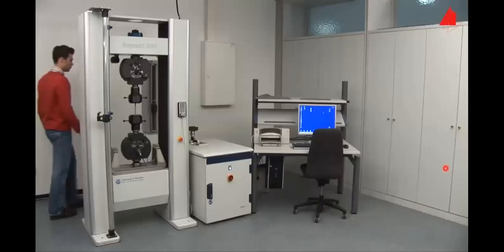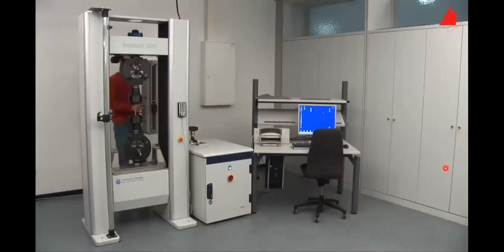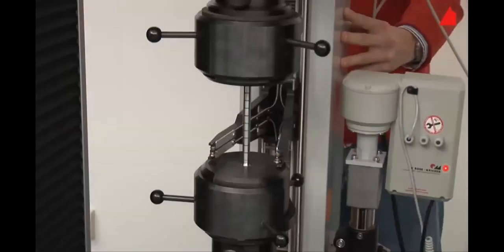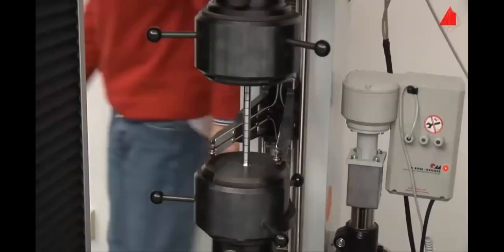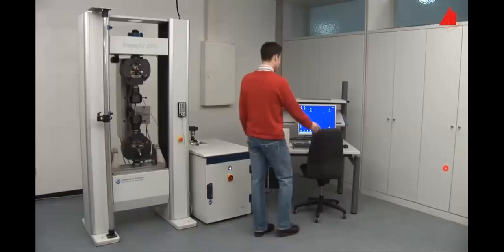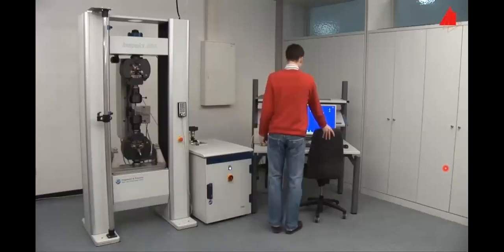Okay, so it is fitted now. Next step, he swings the extensometer into its working position and checks that everything is correctly prepared. Then he selects all necessary advanced machine settings, so certain sensors and everything is used in this machine, okay, to get the accurate results. Okay, testing parameters on the control computer.